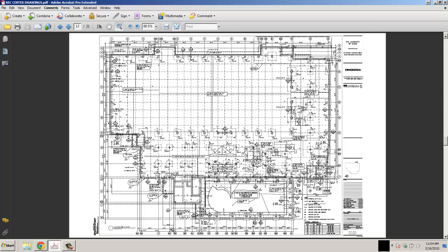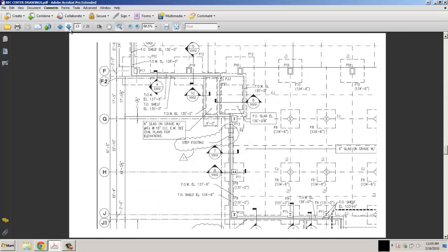So each of these columns is designated by a number or a letter going this way. So column line D6 would be right here. No column there, but when you get down here, you've got a column line D10 or whatever that number is there. So if you wanted to identify that column, you could do it. It's just some blow-ups of the locations. So there's a column line G, which is this run through.